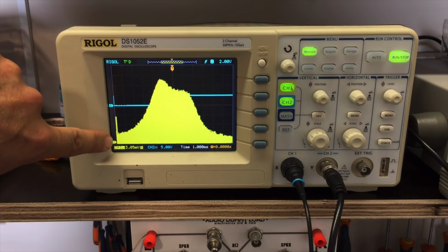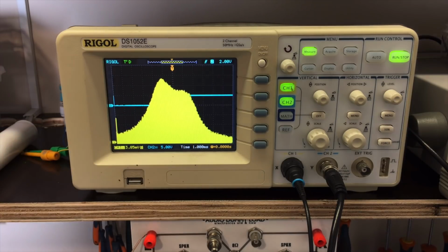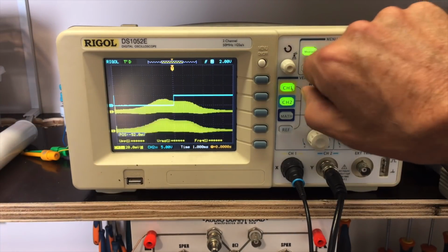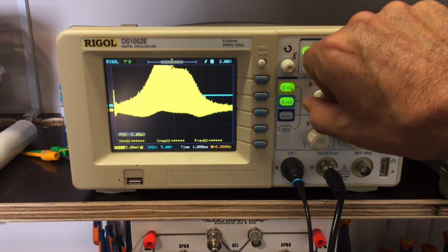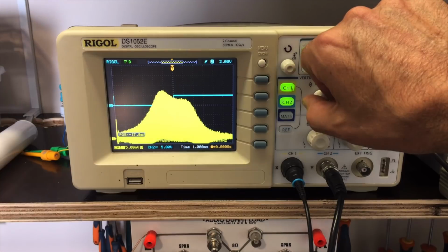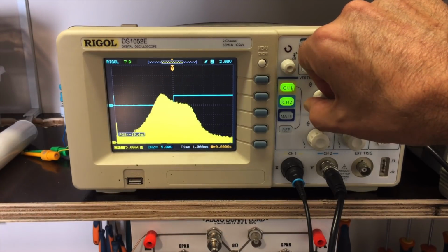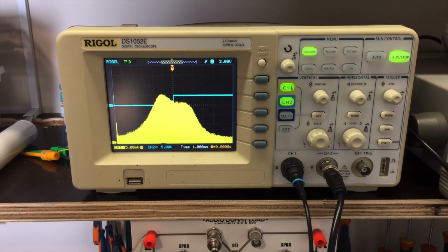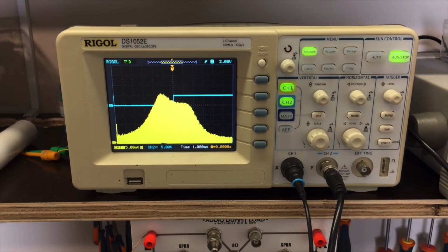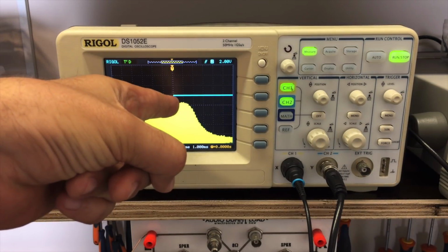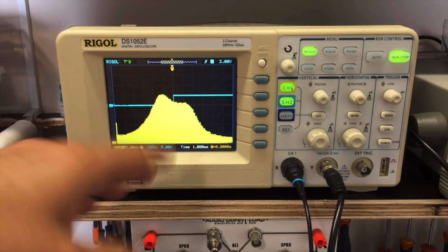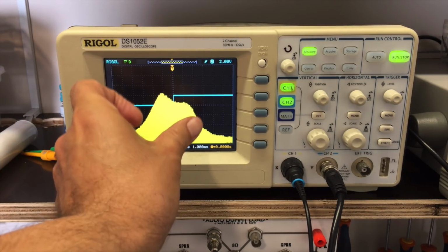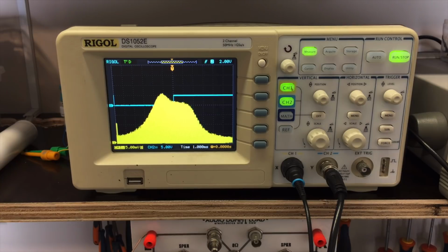At 460 kilohertz, obviously this is not what we get first time round. You get something like this, right? But if you adjust the amplitude and you bring that down, because you're only interested in the section above 0, right? That's what you're getting. And that means that at 460 kilohertz, it's not quite on a peak, but we can see sort of a double hump. This is the width of the IF.